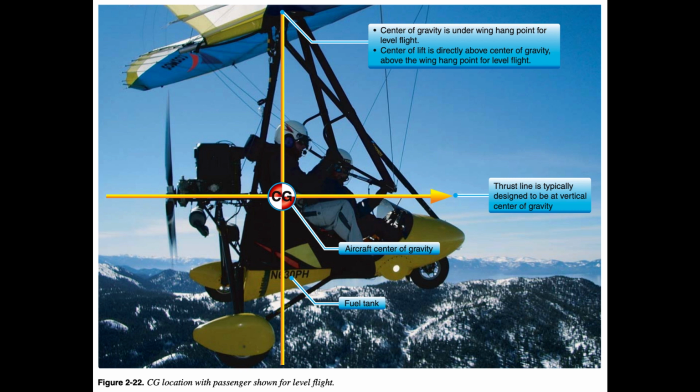However, the WSC wing is higher above the fuselage/carriage and, since most of the weight is centered in the carriage, the CG is well below the wing. In a two-seat WSC aircraft, the second seat is typically behind the pilot's seat and the CG is usually located close to the rear passenger seat. Therefore, the CG location does not change significantly with a passenger. Fuel tanks are typically located near the vertical CG, so any difference in fuel quantity does not significantly change the CG fore and aft with different fuel quantities.